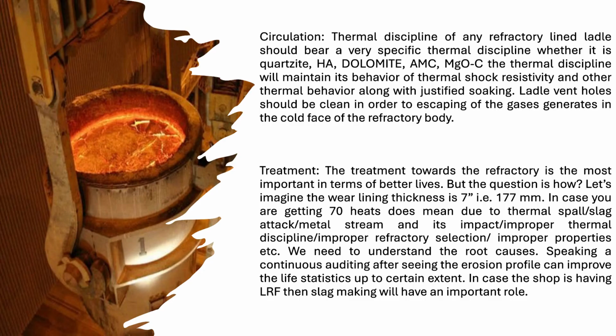Circulation. Thermal discipline of any refractory lined ladle should follow a very specific thermal discipline, whether it is quartzite, high alumina, dolomite, AMC, or magnesia carbon. The thermal discipline will maintain its thermal shock resistivity and other thermal behavior along with justified soaking. Ladle vent holes should be clean in order to allow the escape of the gases generated in the cold phase of the